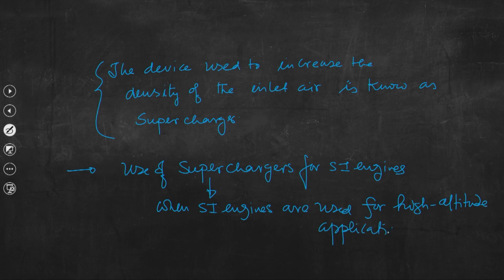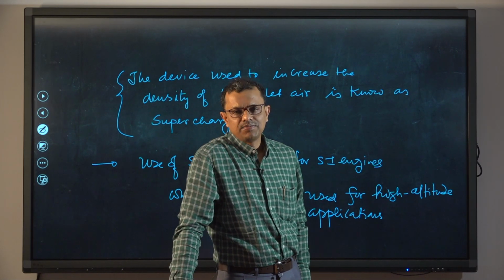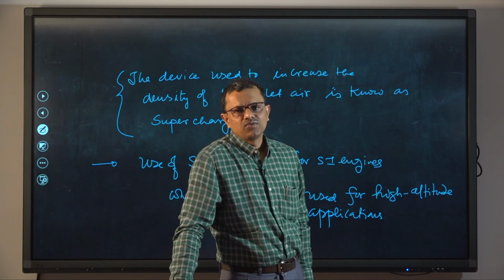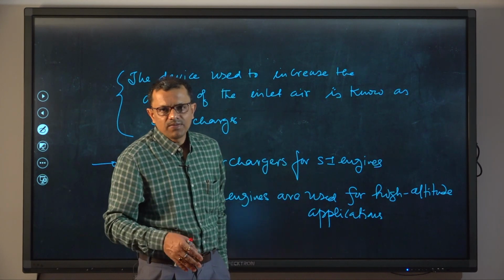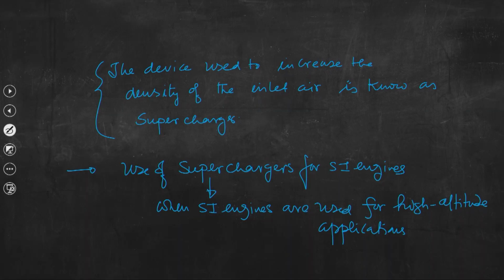That means an SI engine based aircraft or airplane can use superchargers without inviting problems associated with detonation. Okay, this is the most important point that I had mentioned.